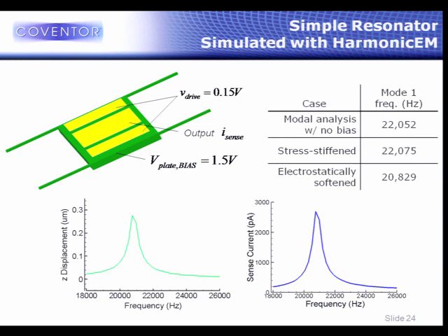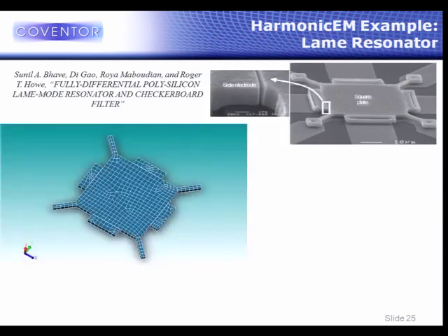versus frequency. So with these outputs, we don't have an example here, but one can model this resonator as a two-port network, and you can use two-port network theory to come up with the impedance matrix for this two-port network using this solver. And so this is a new capability, and once you have that two-port network impedance matrix, then it's some more algebra to get from there to S parameters that you'd want for a resonator.